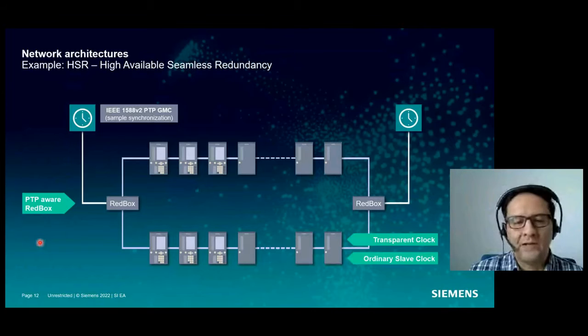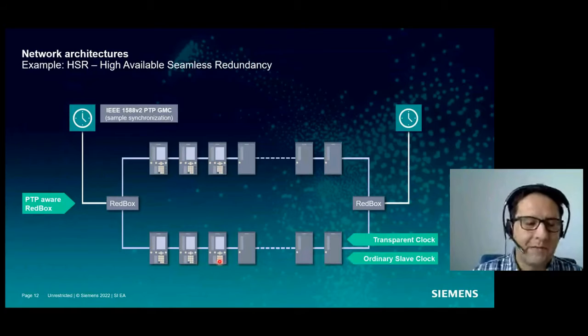The new functionality that we have here in our merging units and our relays is that we have now the transparent clock functionality that permits to have the HSR ring topology.